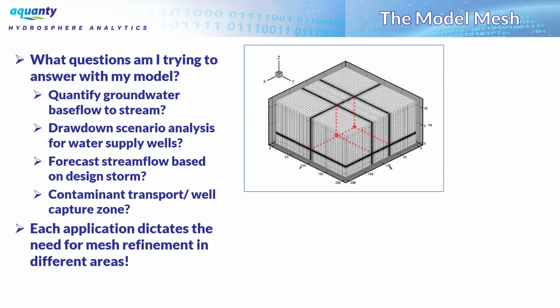If we look at this image on the right, if we had some pumping wells nestled right here in the middle of the model, and we were to use a local grid refinement approach, which is common in MODFLOW, for example, the end result is that we're going to have all sorts of refinement that extends out to the edges of the model domain. And so these areas that I've circled, these basically are areas where we have lots of extra nodes, even though they're not in an area of interest, which is centered around these interior pumping wells.